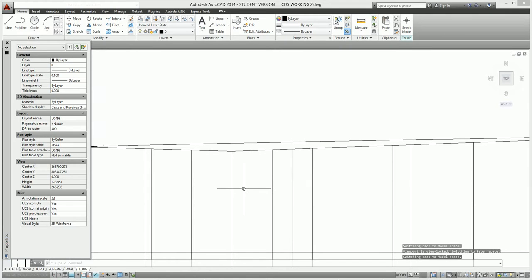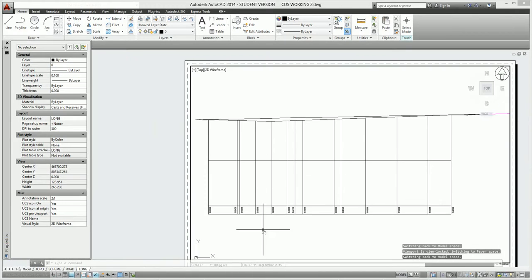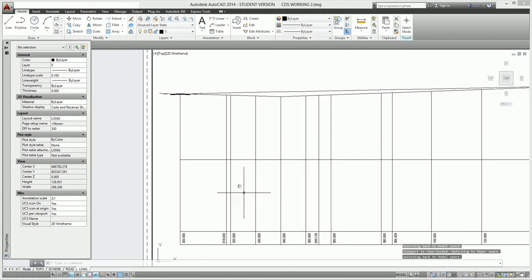So I'm going to be starting my vertical curve at 20 actually. I thought that was a pretty good place to start, and I'm going to have a 40 metre long vertical curve. So I'm going to go from 20, the IP of the grades, my intersecting grades for when I start to go up to the end, is going to be at 40, and my vertical curve will finish at 60.